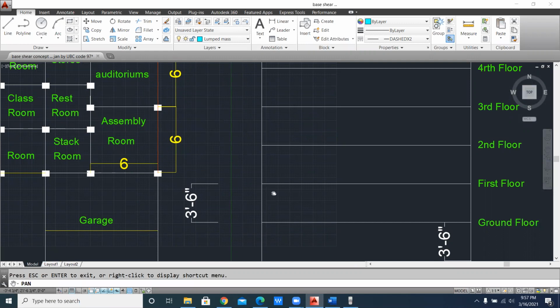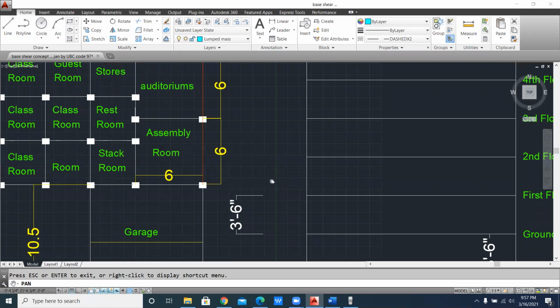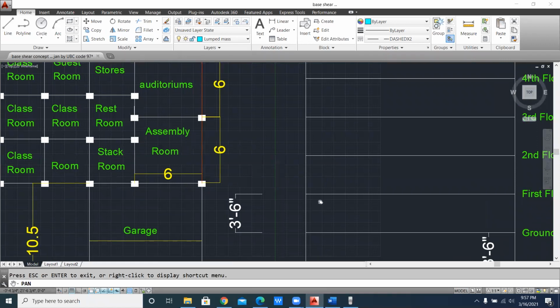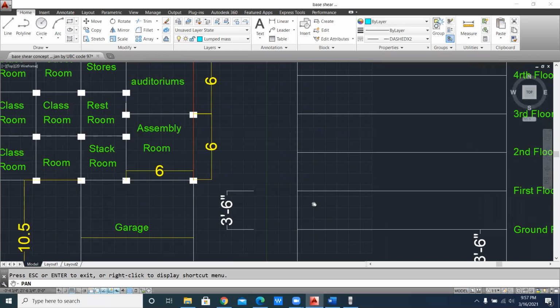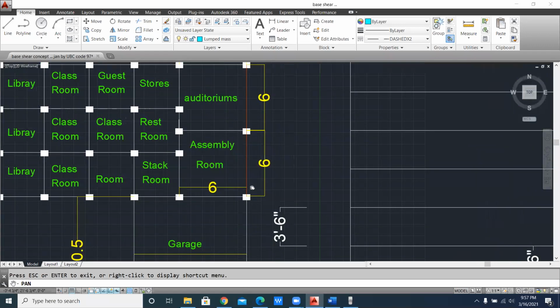When you multiply with the thickness, then you don't have to give any length, because SAP considers itself as just kilonewton per meter. So kilonewton per meter, it will take per meter length as its own. Okay, you have to give their height, so into the height minus depth of the beam. That is for the calculation of the SAP. If you want to find out the parapet, then 19.2 multiply by thickness of the wall and height of the parapet. Okay, it is up to you.